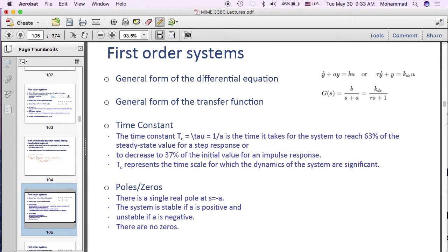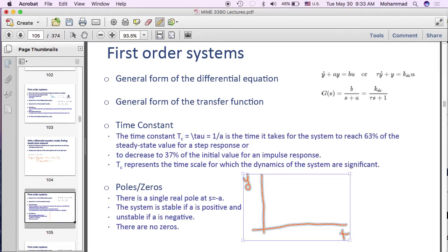I think we did it, let's just do it one more time. So if this is time versus response of the system, if you have a unit step, the response looks like that. So it goes up and settles. If you have some initial conditions, so if you start off here instead of from 0, but no input, it basically takes the same trend and approaches 0 with the same speed. What I meant to do is a mirror image.